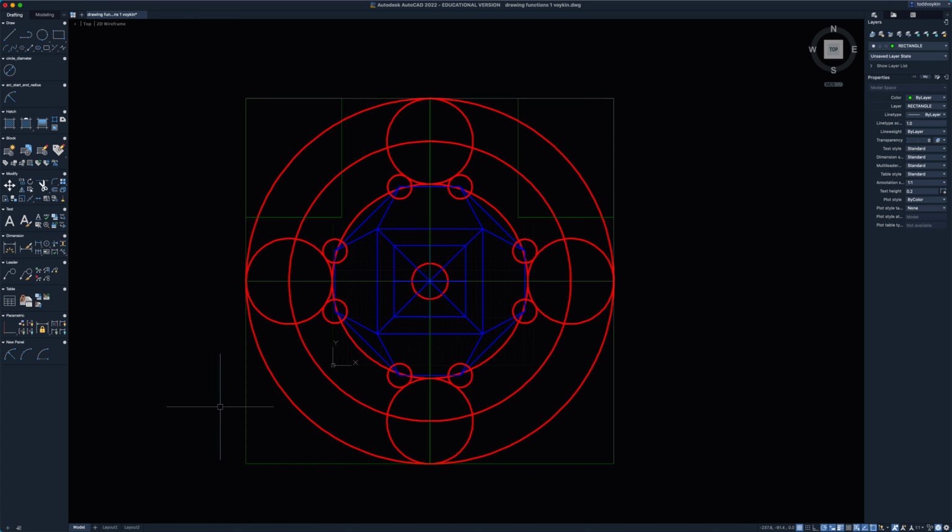enter. And now if I do it again on the bottom left, we'll deal with the X first, to the right, which is positive, and going up, which is positive, so it'd be positive 200, and you don't have to actually type positive, just 200, comma, 250, enter, and that one's done. Last one, coming from that corner, it's going negative in the X, positive in the Y, so negative 200, comma, 250, enter, and we are done.